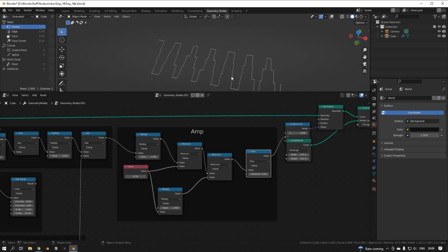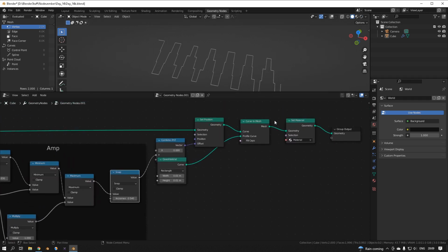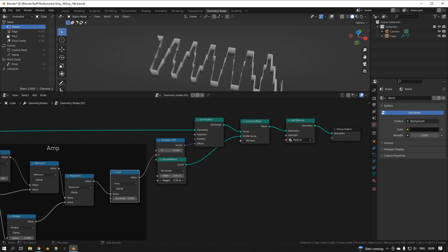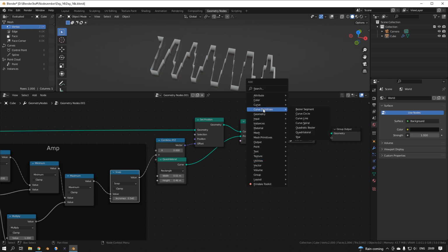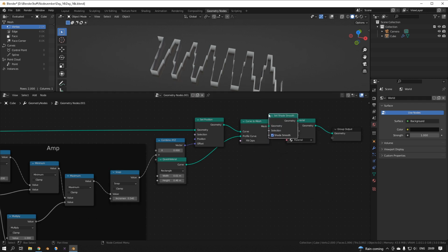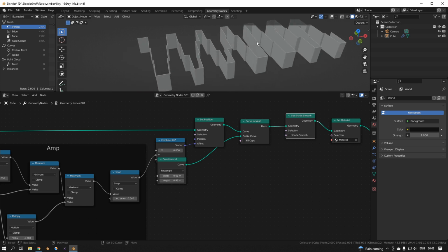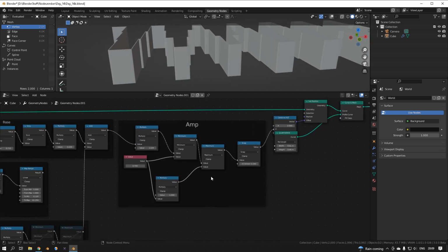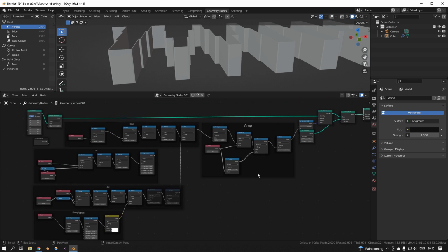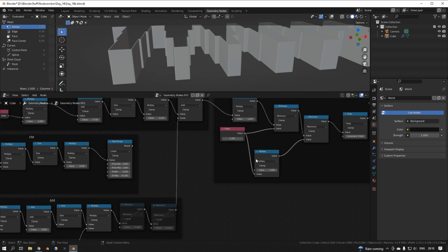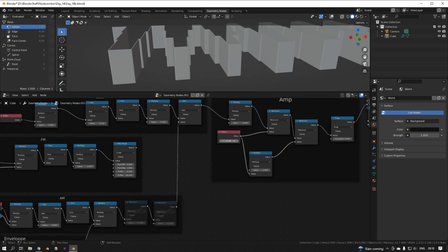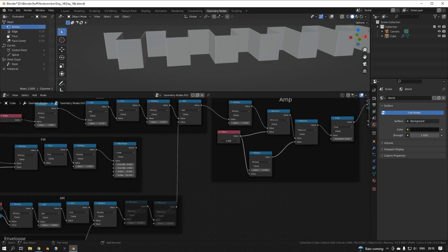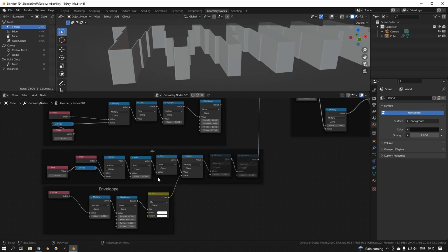Let's turn this off. Let's go here, and if I then go to curve to mesh, can I adjust the height? And I want to turn off smooth shading, so go to mesh, set shade smooth. I turn it off. So you can model actually with waves. So I want to decrease the amplitude. Oh, maybe I do that here. Let's see.